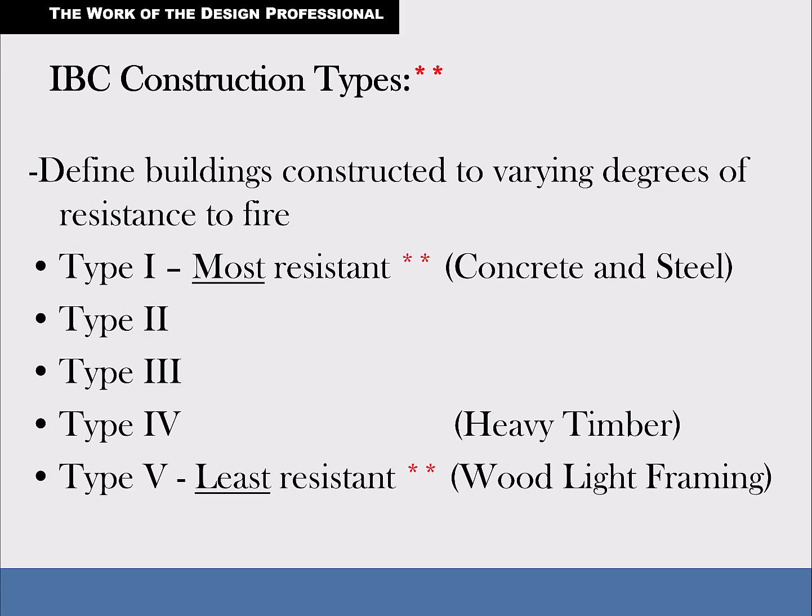Now, the heavy timber type 4, IV, there, is a special case. Yes, it's better than type 5, just by order, but it's actually better than some types of type 3 construction, because a great big heavy wooden beam takes a lot for that to burn through. It has a certain burn rate, and so that's why you can have a great big heavy beautiful looking wooden beam in a church and it's fine, because it will take a long time to burn through that thing, and so the egress is not a problem there.